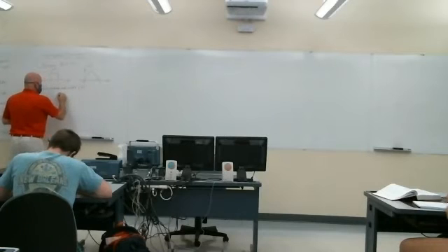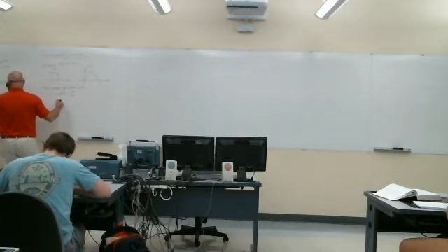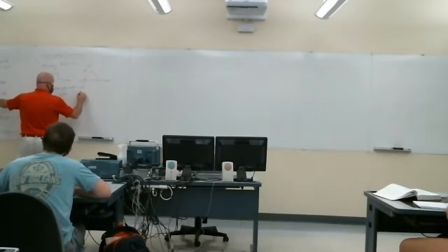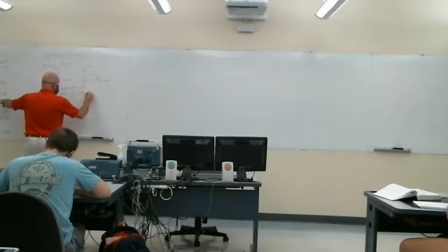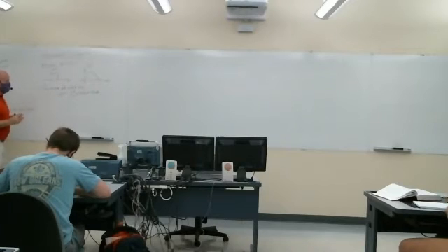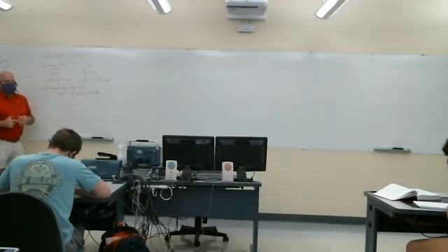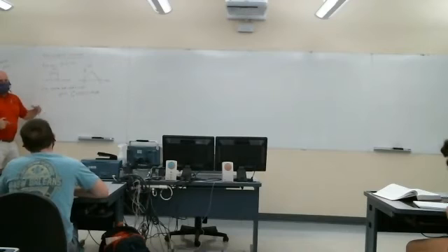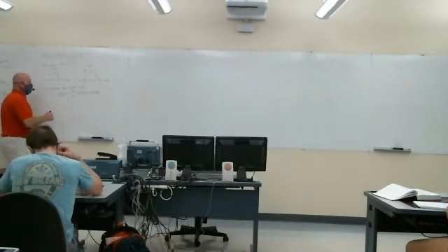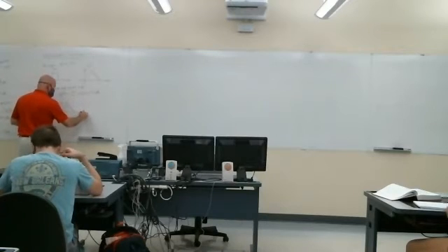Okay. So we're going to evaluate, from minus infinity to infinity, the second form, h of tau, x of t minus tau, d tau. Now the first part of this is really easy. I'm going to sketch these two functions, h of tau and x of t minus tau. t is the variable, tau is my integration variable. Sketching h of tau is simple. That's just a change of variables.